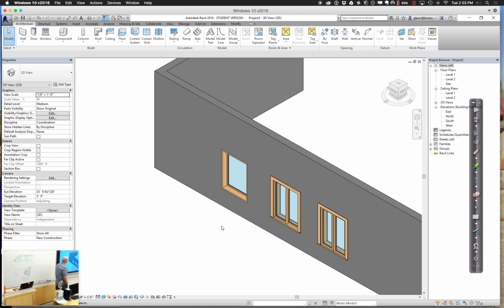How about in terms of ventilation? Okay, so this one's fixed, the glass doesn't move. This one panel slides past the other. This one, they both swing open. Okay, so if you were thinking about trying to capture some cool natural breezes or something like that and use natural ventilation, this one's out of the question. That's not doing you any good at all. That lets the light in and the heat in, but no ventilation. This one sort of opens halfway. Okay, this opens the full way.